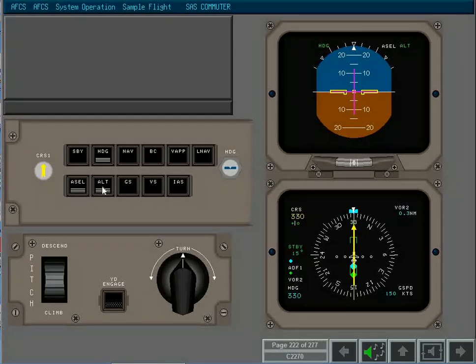ATC now clears you to continue climb. As your speed difference is not great, use IAS and the AP pitch wheel to resume climb. Use the pitch wheel as the aircraft arrives at 1,000 feet below the selected altitude. The altitude alerting system sounds the C chord.